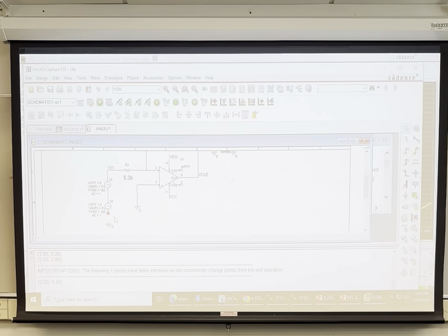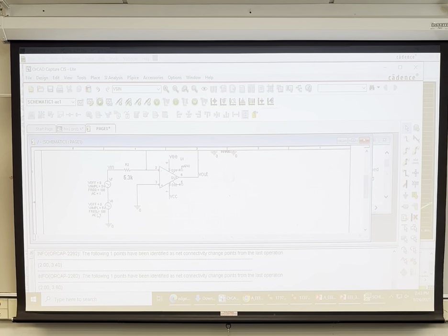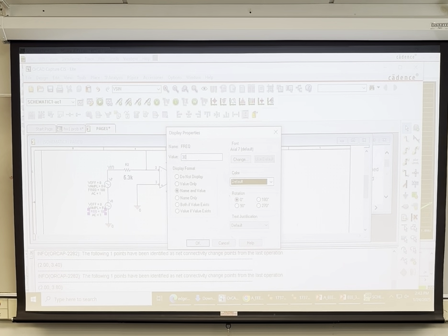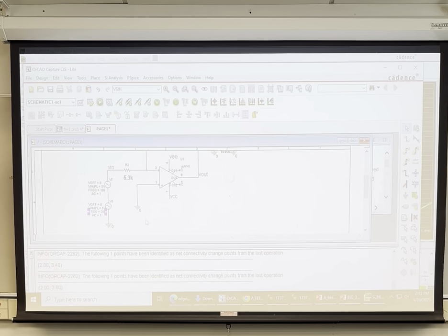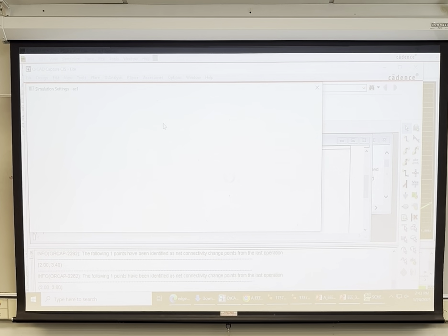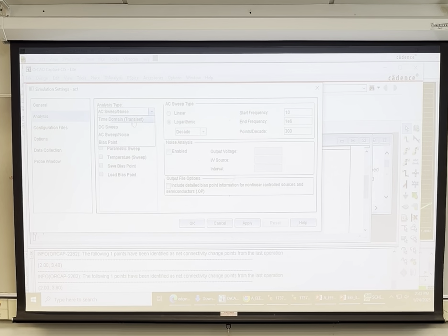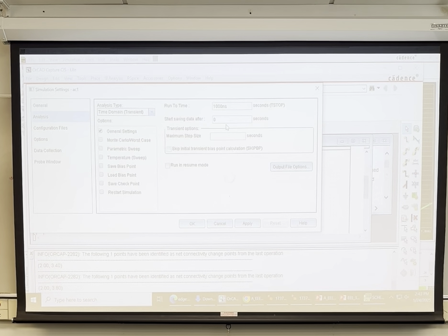And then our ground wire. And you can set this offset to 0. The amplitude is 5 volts. And what's this interfering frequency? 30 kilo. We'll set this to 30K. So we have two sources on the input for transient with both 5 volt amplitude. And now our simulation profile, you'll change that to transient.